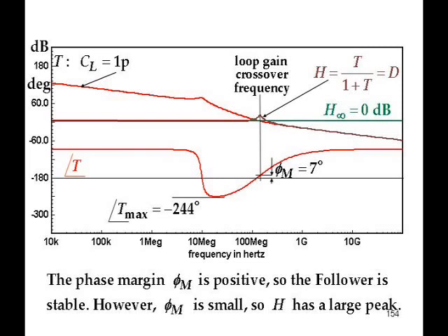Then it has a little peak and it goes into a triple slope, because we got two poles at the same frequency with a high Q. So that little middle region is a triple slope. Then the two zeros come in further up. So the two zeros cancel two of the poles, leaving you with a one-pole final asymptote.